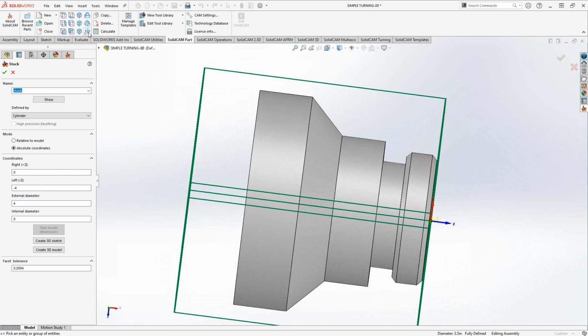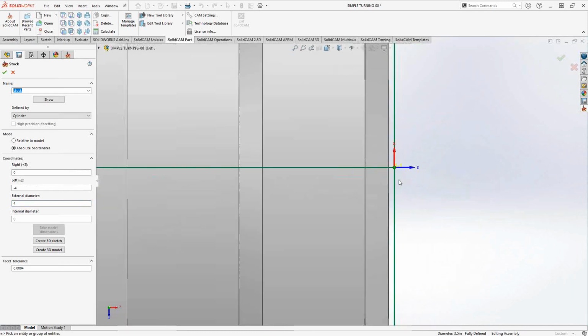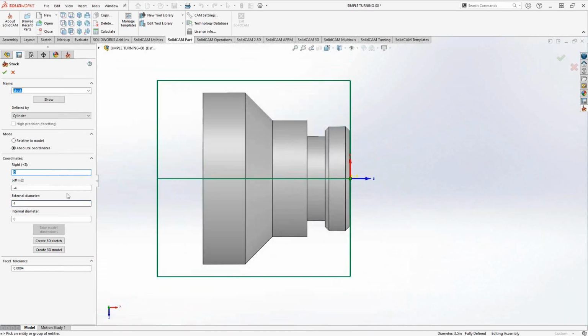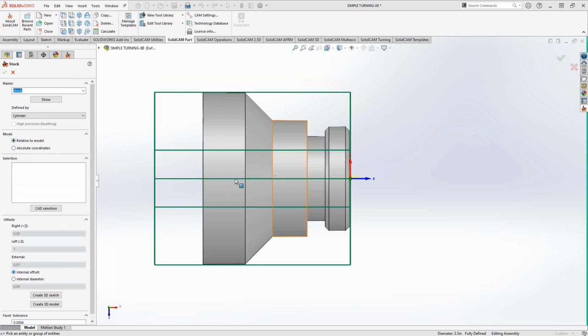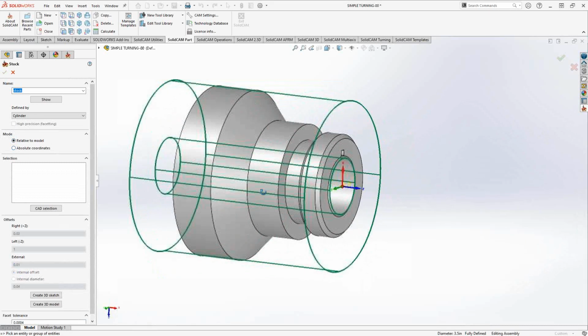So to get that same 20 thou, I either create my coordinate system where I like it, the 20 thou, and then that's my Z equals 0. Or if I had it on the original face, this would have to be a positive number. This would have to be the 20 thou out. So really, again, it's just either you're defining the exact cylinder with the proper sizes here, or you could use relative to model, where everything is incrementally output from the face.